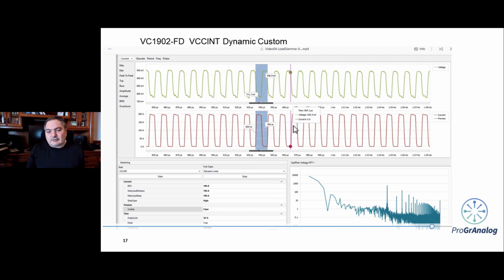We do have a number of demo boards in the lab, and we deliberately keep them untuned because there's all sorts of cool oscillations and weird stuff you can capture. So we're in the business of not optimizing the PDN just so that you can demonstrate what the tool can capture and what it doesn't capture.